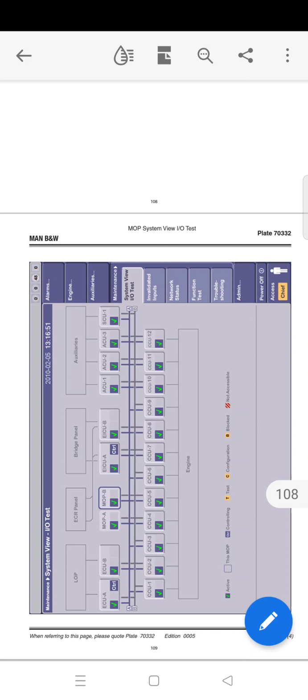The multi-purpose controller contains no hard disk or other sensitive mechanical components, and the software is stored in a non-volatile flash PROM memory. That is, the application software may be sent to and programmed into the multi-purpose controller through the network, and thereby restore the functionality after the multi-purpose controller has been exchanged with a spare unit from the stock.